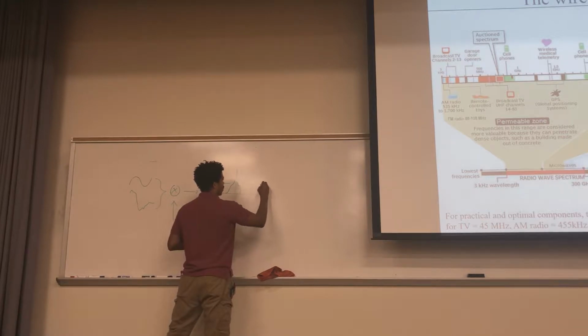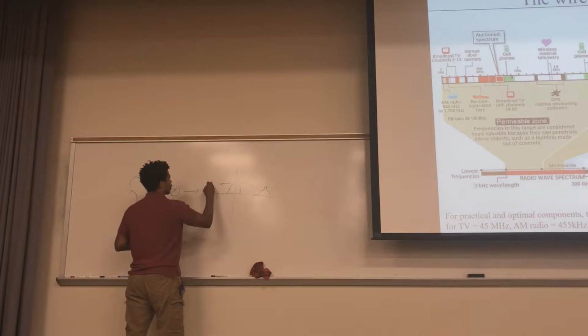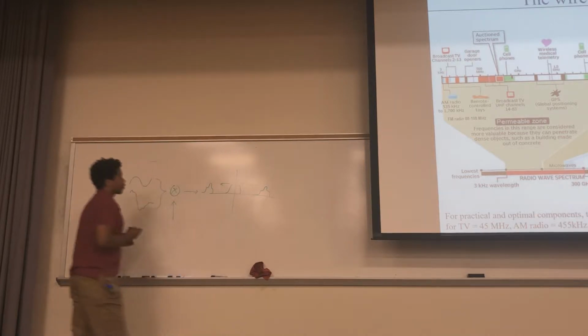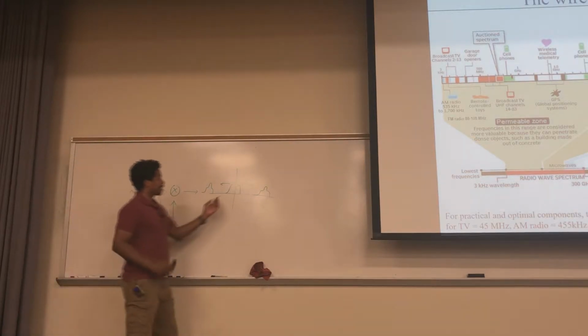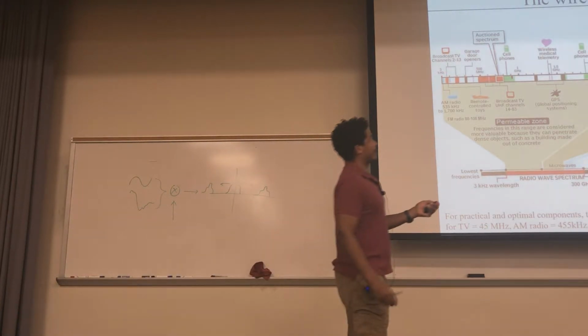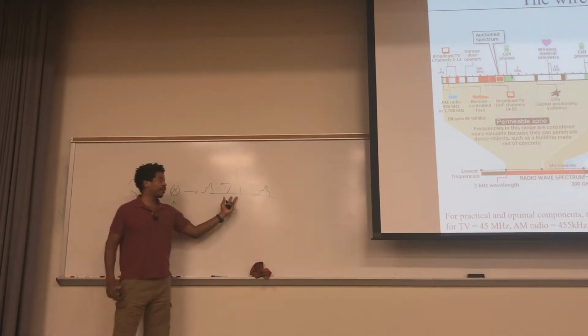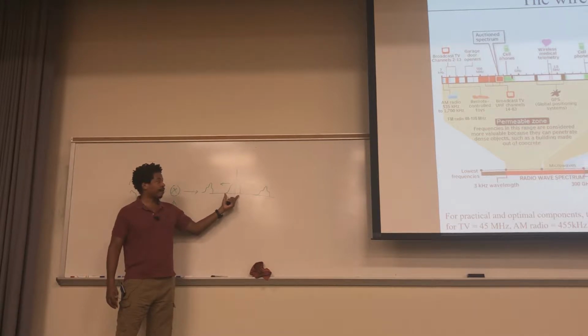So you have another signal over here that's a copy of it, to the right and left. Depending on how far that is, you may actually be going into another nearby band, or your device may interfere with another neighboring device that's trying to get a clean signal. So you don't want to do that. You need to get rid of these guys right here in the end.